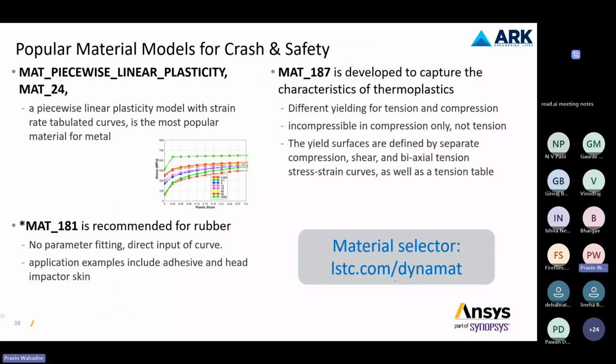Now, similarly, a part consists of material. Any component, when we are defining it in LS-DYNA or any other tools also, generally needs this information: the property and the material property, the physical property, like what the geometry is, what type of element type it is, and what material is being used for solving, whether it is steel or aluminium or a rubber material.